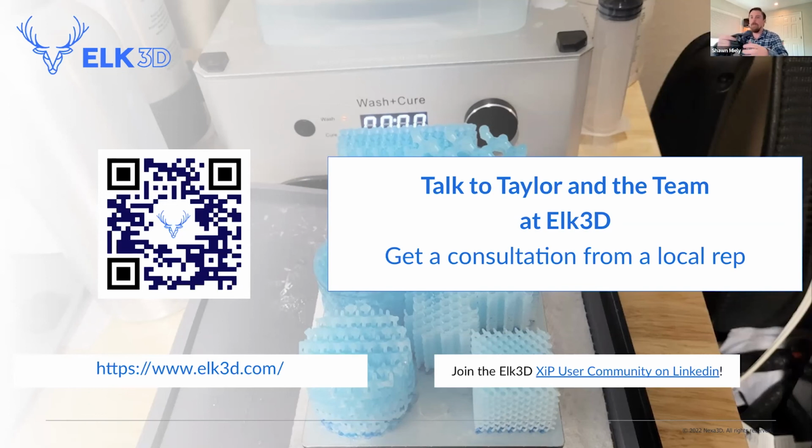If you're using something like this, which is printed in our XABS resin, this is a much slower printing resin. So the trade-off there is that the X45 natural looks really good for modeling and prototyping but is not going to be super durable, whereas this XABS is a really good analog of ABS, so it's going to be more durable.